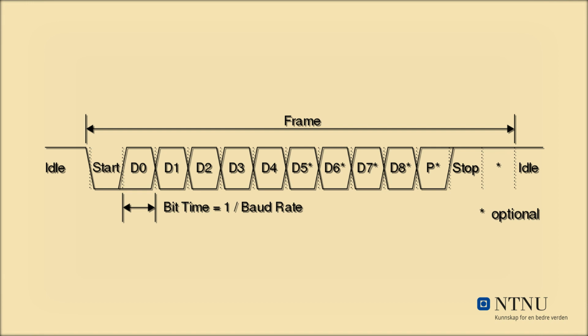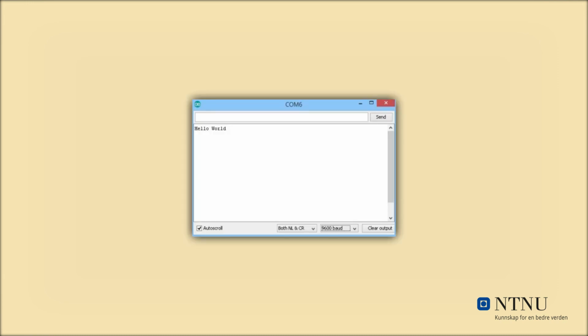The advantage this setup gives is the asynchronicity, exempting the need for any shared clock. The system instead uses start and stop bits to declare each package, which enables communications as long as the baud rate is set the same. Another advantage of the use of UART is the possibility to read the serial output via a computer using a USB connection, making troubleshooting easier.